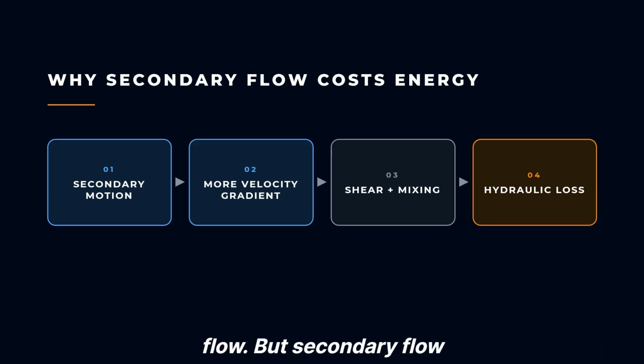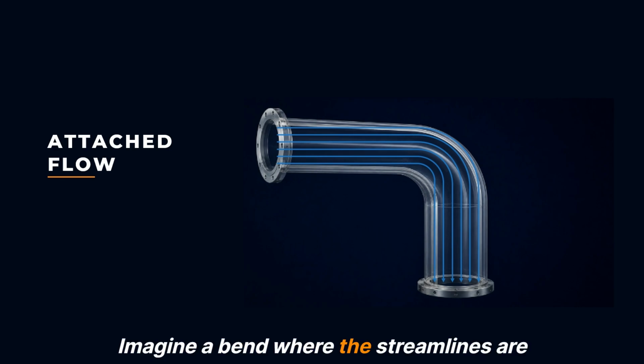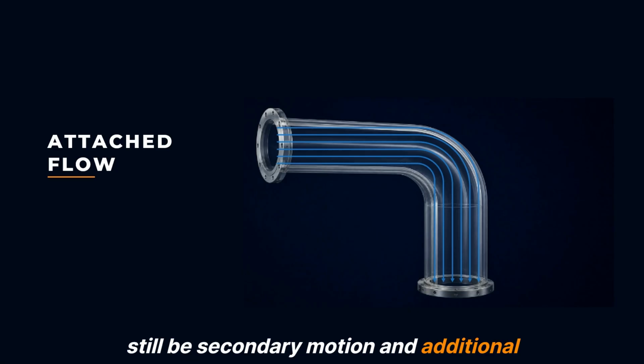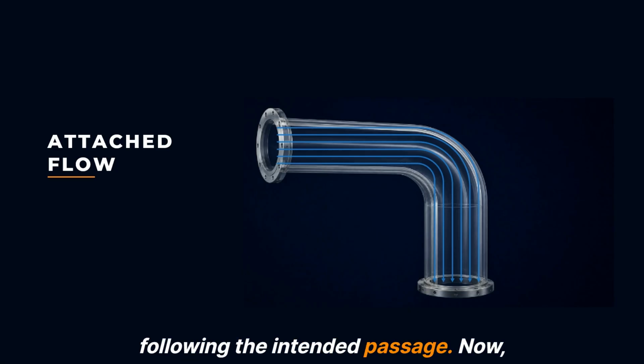Attached flow. But secondary flow is not the only possible source of loss. Imagine a bend where the streamlines are still able to follow the walls smoothly. The flow remains attached. There may still be secondary motion and additional resistance, but the fluid is generally following the intended passage. Now, let's make the turn more severe.